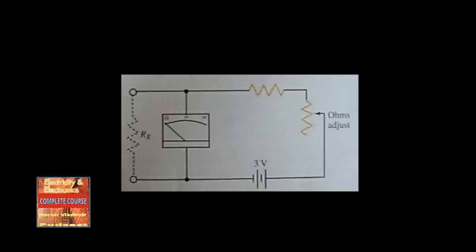A shunt ohm meter is connected as shown in figure 2-14. In this circuit, the unknown resistance, or Rx, is shunted, or connected in parallel, across the meter. Low values of Rx cause lower currents through the meter. High values of Rx cause high meter currents. When the ohm meter is connected in the shunt position, the indicating needle deflects from left to right in the manner of the amp meter and voltmeter. Zero resistance is on the left. The scale increases from left to right. Figure 2-14, schematic diagram of a shunt ohm meter. Note that the meter reads in the opposite direction of other ohm meters.